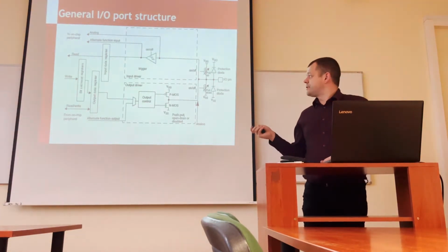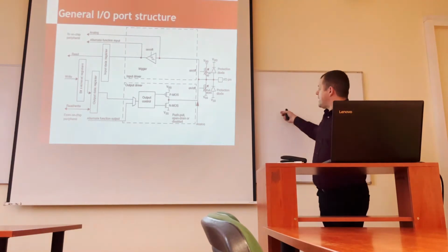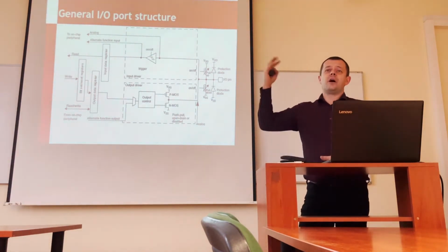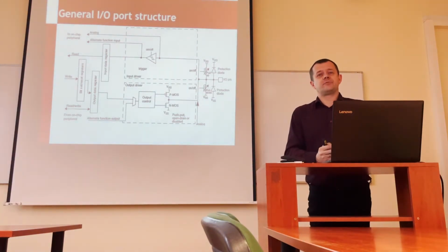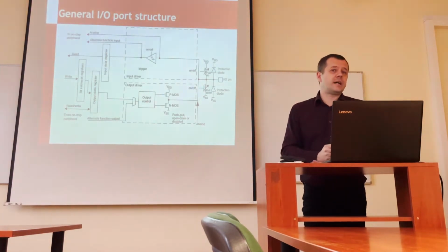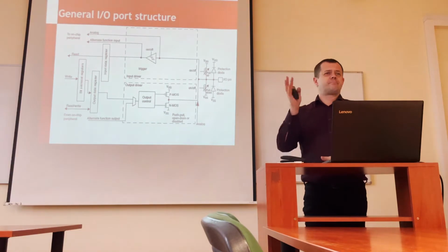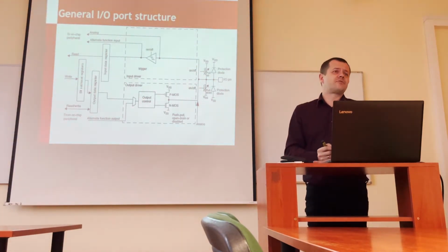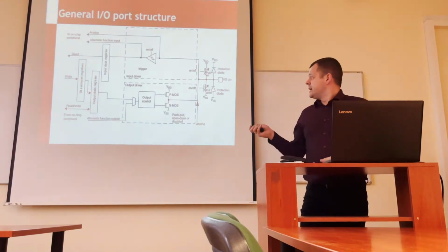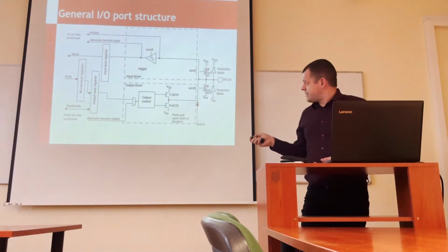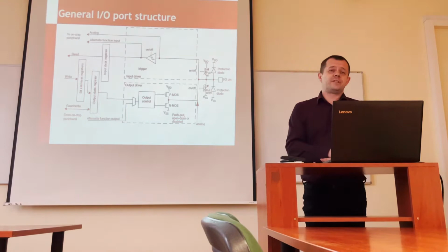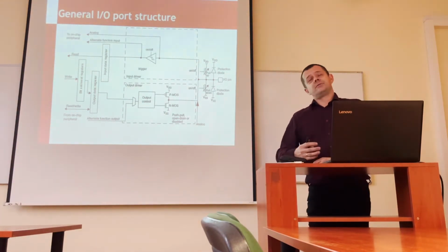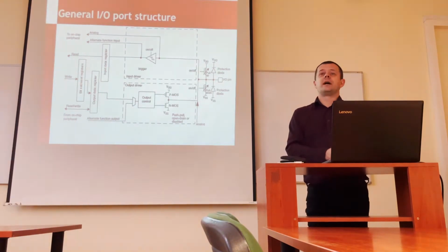So if you wanted to connect one output from a NAND gate, NOR gate, whatever gate, to other gates, then no more than 10 was the limitation, because the standard TTL was capable of driving just 0.4 milliamp or something like this. This was the standard TTL strength. It was so weak. Today we have CMOS, and its transistor output stage is usually quite strong, unless you take a very ancient microcontroller in your design.